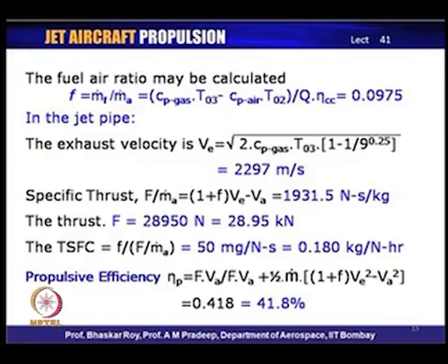The corresponding specific fuel consumption, TSFC, can also be found, and this comes out to be of the order of 50 milligrams per Newton second, also written in terms of kilograms per Newton hour.